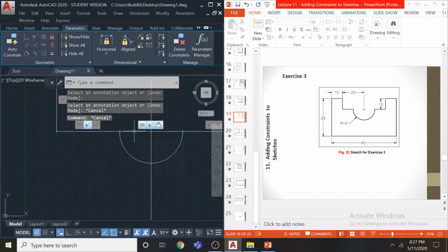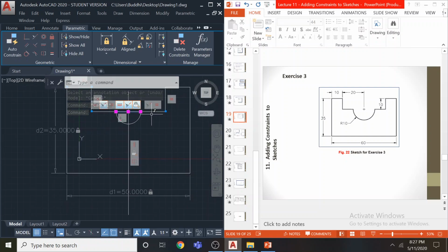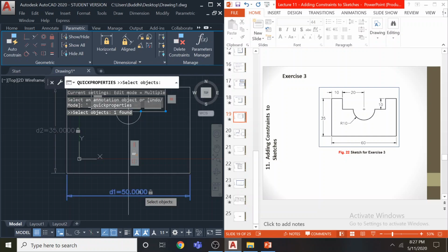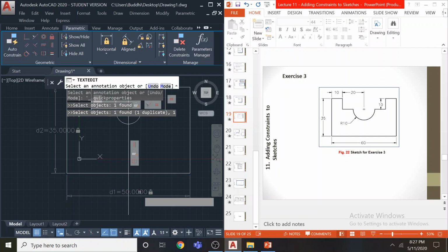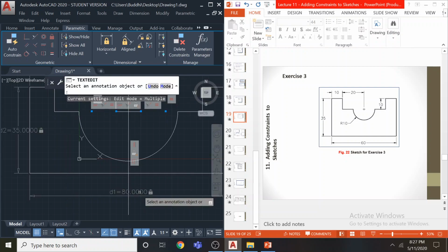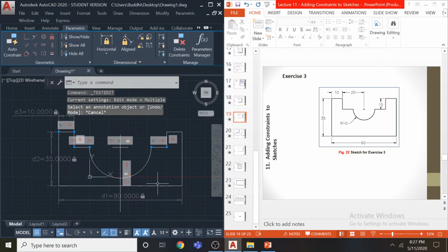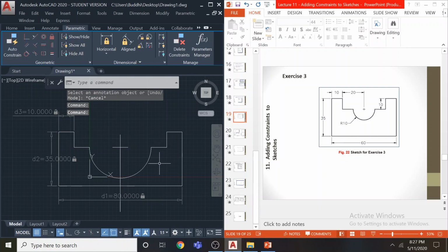This line should be a center line, then you don't see this continuity. Then if you press it to 80, it should nicely adjust. This is the whole idea of parametric drawing. So you can quickly adjust your designs without wasting much time.